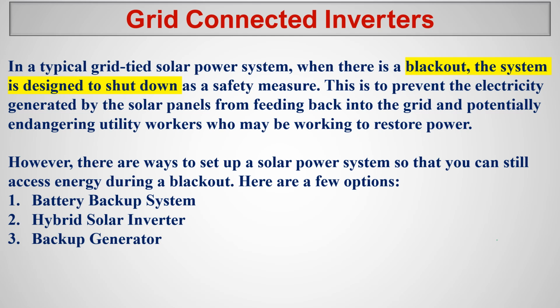One thing is that grid connected inverters use the reference voltage and frequency from the grid to turn on the inverter. That's the first thing. Second, for safety reasons, we purposely make the grid connected inverter shut down whenever the grid is not available, because we don't want it running during the power shutdown in developed countries.